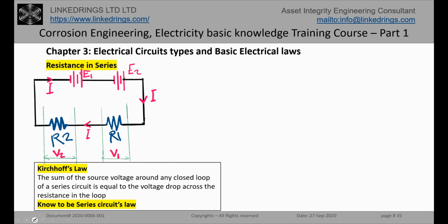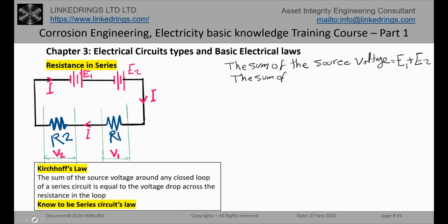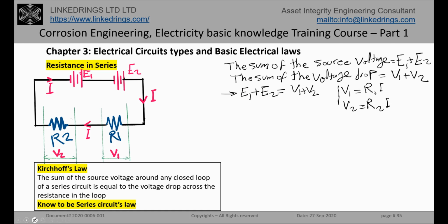Kirchhoff's law is known to be the series circuit law. So let's apply Kirchhoff's law here. E1 plus E2 equal to V1 plus V2. And V1 equal to R1I, V2 equal to R2I.